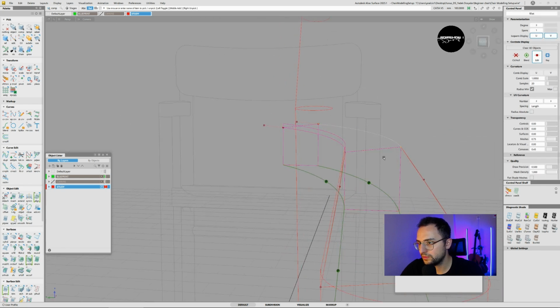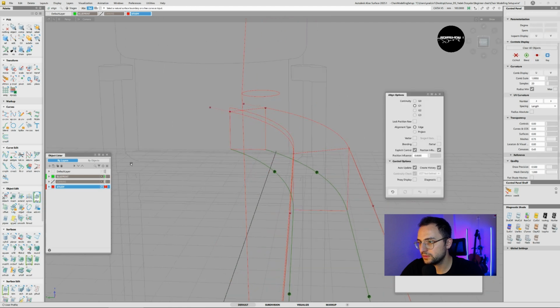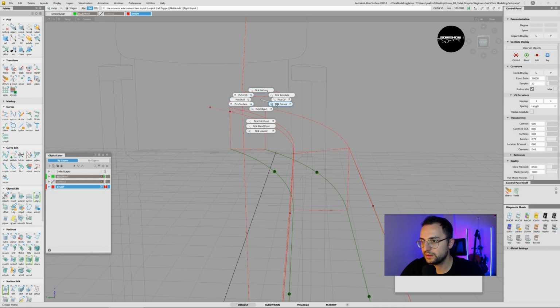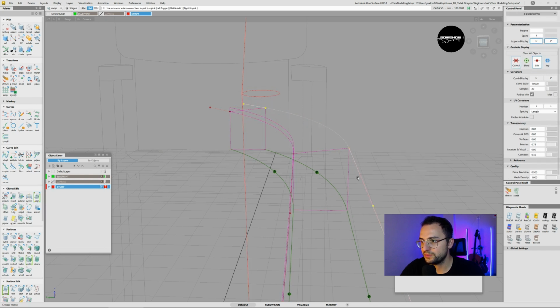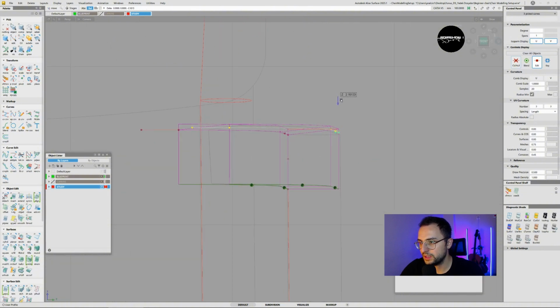The curve. Do we have history behind? Let me do query edit on this fillet. Yes, and then realign that edge to that curve. Pick these curves, go to the front view and lower them down.